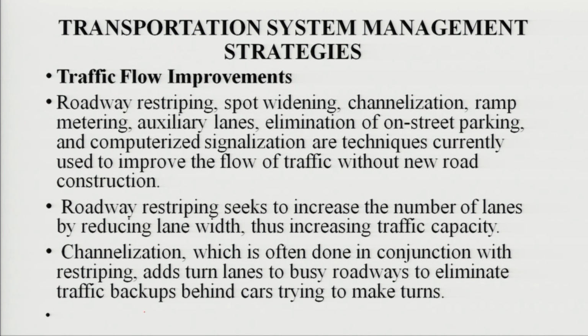Roadway re-striping seeks to increase the number of lanes by reducing lane width, thus increasing the traffic capacity. Channelization, which is often done in conjunction with the re-striping, adds turn lanes to busy roadways to eliminate traffic backup behind cars trying to make turns.